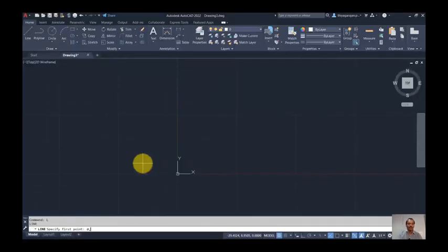I'm going to start the line from the origin. Move the mouse, it will go in any direction without any restrictions. Okay, you can draw anything. Now, if you want to control the movement of the mouse only in X and Y, or otherwise I can say, you can see the cursor shows the 4 angles 0, 90, 180, 270. If you want to control the movement of the mouse only in these 4 directions of the cursor, you can use F8. What is the use of this key?